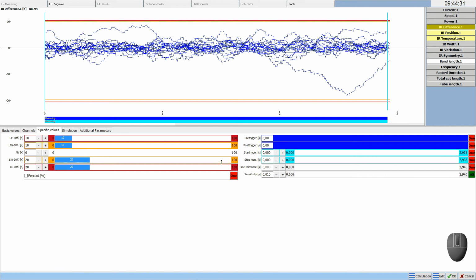If monitoring has just been switched on, this button must also be pressed once so that the limits are generated at all. Since the limits cannot be calculated optimally for every channel in every process, it must be checked that the limits were set optimally for the process each time the limits are relearned automatically with the calculation button. If necessary, the limits must be adjusted. The Calculation Add button eliminates single limit violations. It sets only the limits automatically again which were cut with the parameter curves. With this you have now the basic knowledge to teach in limits.